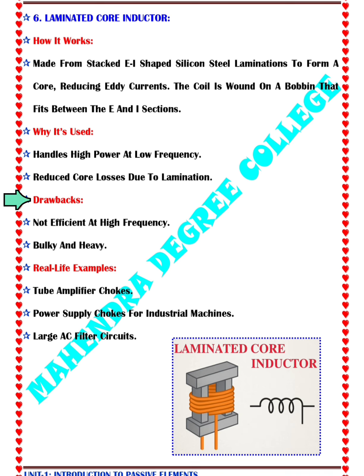Next, we will discuss the drawbacks of laminated core inductor. Not efficient at high frequency. It means laminated cores are mainly made of silicon steel, which has higher core losses at high frequencies.